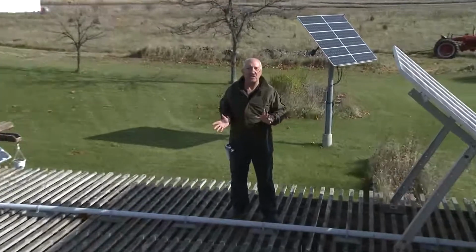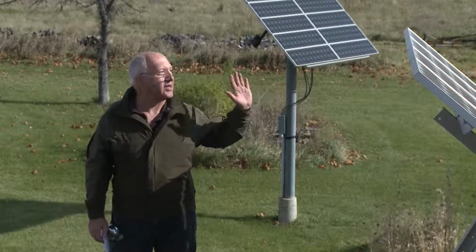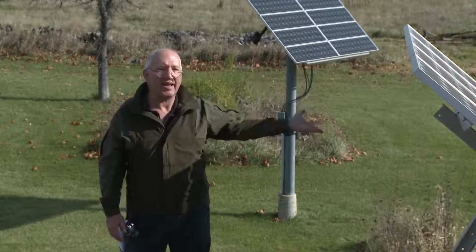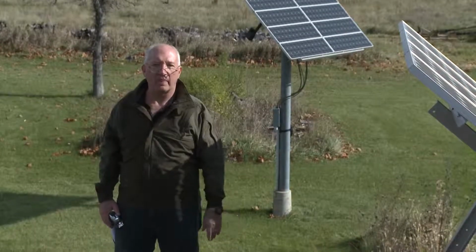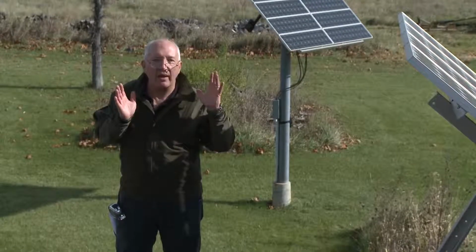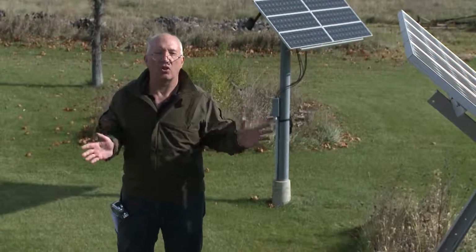There are ways of fudging this and doing it simpler and easier with one single calculation. Let me give you an example, and you'll have to play with this for your specific latitude. With the 30-degree latitude, instead of using 9 a.m., if I use 10 a.m., with an azimuth of 0 degrees, so I take my 10 a.m. elevation and just do one calculation, similar to the first calculation we did before, I end up with 5.2 feet instead of 5.25 feet. You know what? That's like cutting it with an axe, marking it with a piece of chalk. It's close enough.